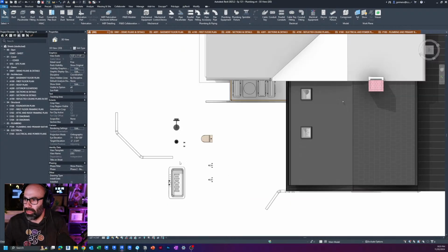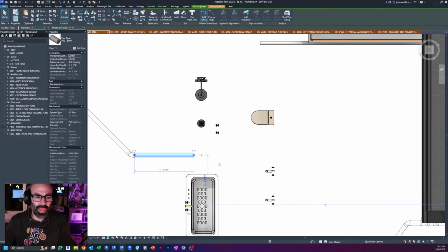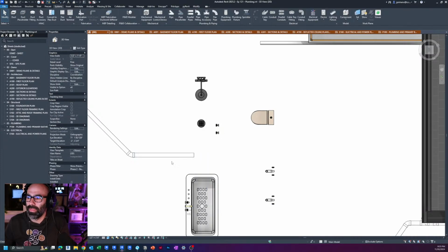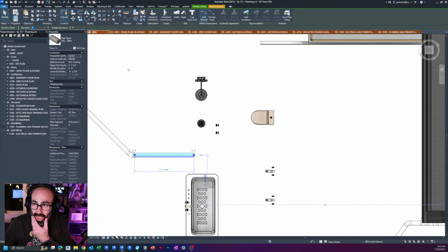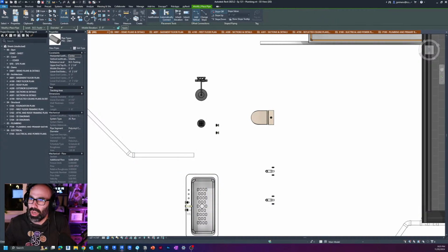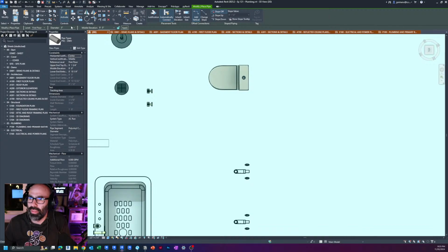Let's say I'm going to start with what I think will probably be the biggest one, which is the toilet. It might be the biggest drain line. So I'm going to create a similar pipe from Systems, Pipe, and I'm going to make this one a 3-inch. This one's going to be first floor, and let's just say the middle elevation is -1 feet. I'd have to cut a section to remember exactly where.